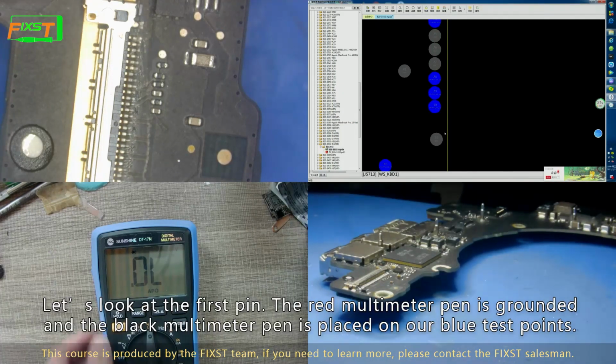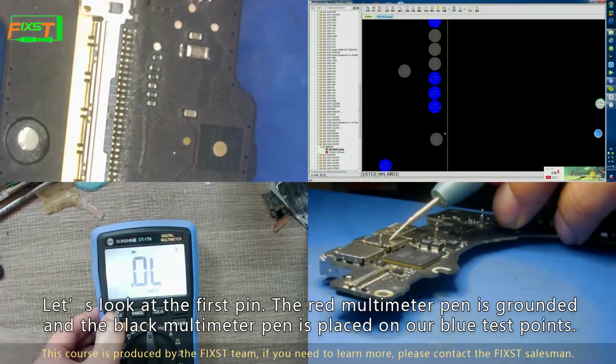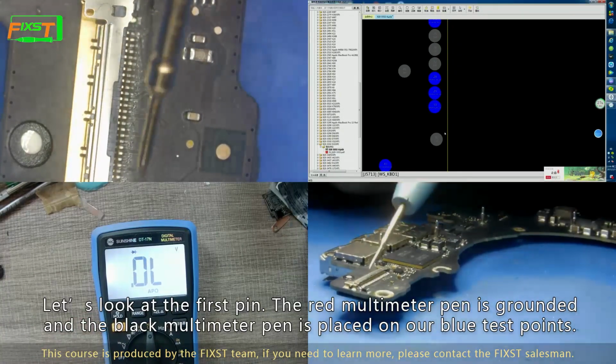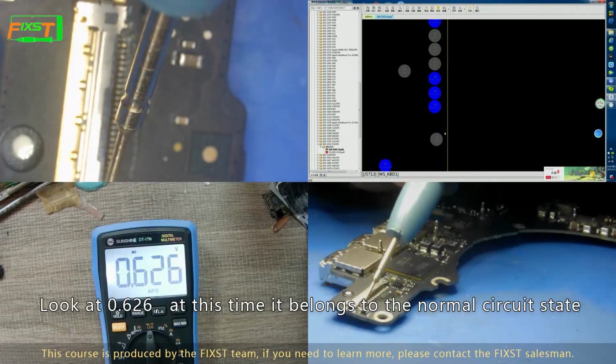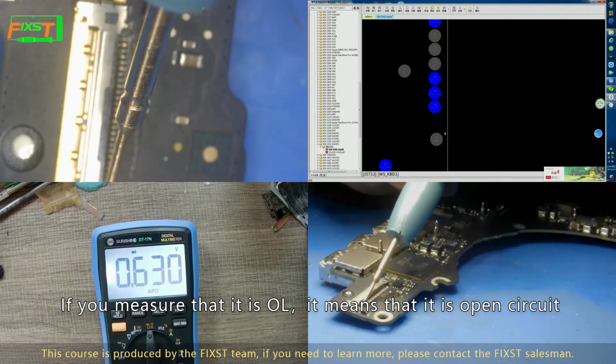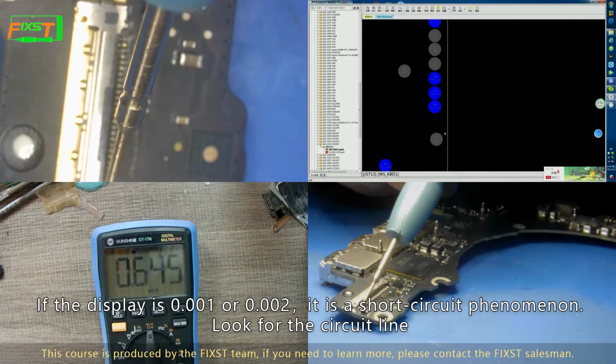Let's look at the first pin. The red multimeter pad is grounded and the black multimeter pad is placed on the blue test point. Look at the 0.626. At this time, it belongs to the normal circuit state. If you measure that it is OL, it means that it is an open circuit. If the display is 0.01 or 0.02, it is a short circuit phenomenon.